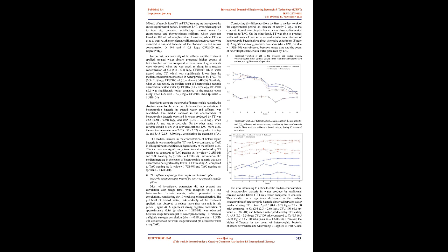Evaluation of pot-type ceramic candle filters. The most relevant results of POU water treatment using pot-type ceramic candle filters, considering contaminated, A1, and chlorinated, A2, water sources are graphically presented in Figure 3. Treatment of A2 using these systems fitted with traditional ceramic candle filter, TT, produced water with a median concentration of 0.30, 0.22 to 0.33 mg/L of free chlorine. It is important to remind that A2 was not dechlorinated before being added to the top reservoir, which resulted in the remaining concentration of free chlorine following the 24-hour period.